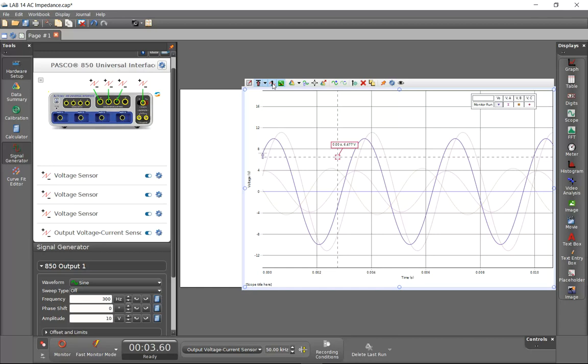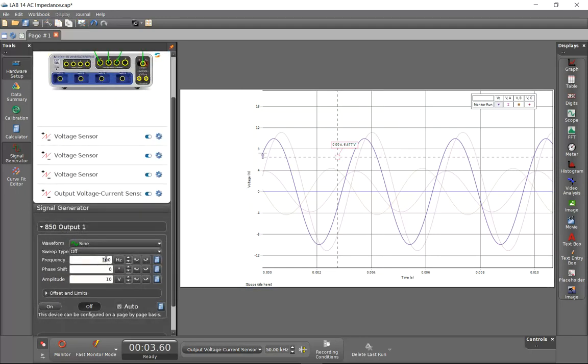So now we look at this, and you have to choose your frequency. And you have instructions on how to choose the frequency. It says, and I'm going to quote, adjust the frequency generator until the voltage across the inductor and the voltage across the capacitor are both over 4 volts, but not equal to each other. So I look up here and I say, okay, they're both over 4 volts. They're not equal to each other. One is 10 and one is, actually it might be under 4 volts. So what do we do then?